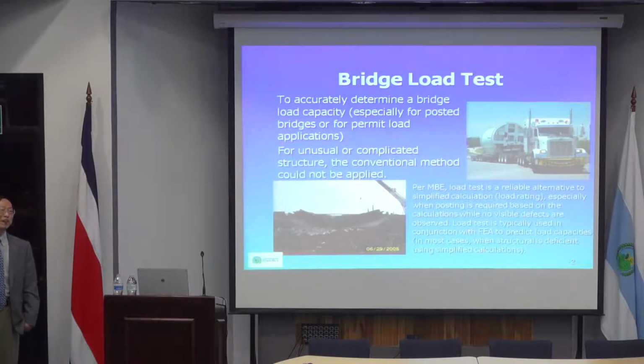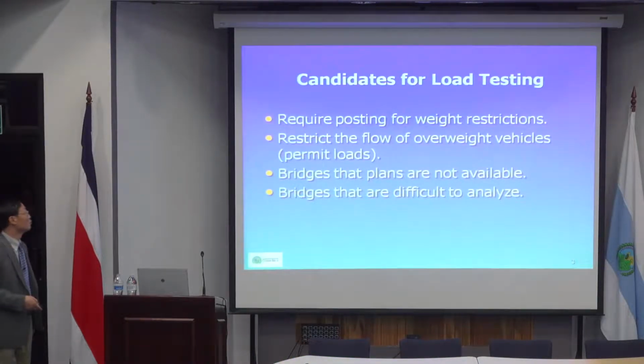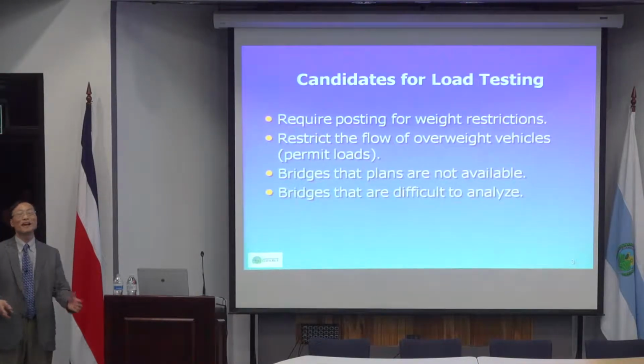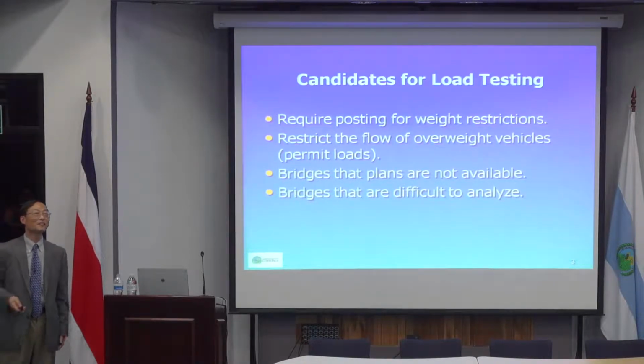And that explains why a load test is a very good avenue to save costs. In other words, if you don't see a problem, most likely you will not face a problem. Of course, if you don't do a load rating calculation and simply do inspection, probably you will not see a problem in the first place. Again, a candidate for load testing is a bridge where, when you do calculation, it says not safe, but in reality, it is safe.